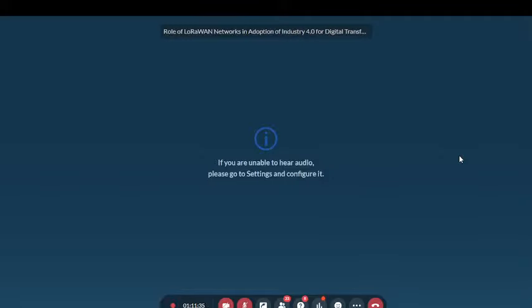These are available in the market, where you can get these temperature sensors converted, and then they can send data to the LoRaWAN gateway. So we also have a thermocouple to LoRaWAN converter, an RTD to LoRaWAN converter, and also, if the sensor is 4 to 20 milliamperes, then we also have a 4 to 20 milliamps to LoRaWAN converter.